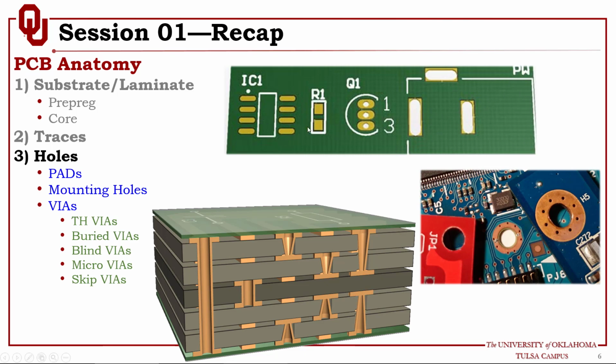And these, they usually call single layer pads for surface mount components, and these are called through hole pads for through hole components. And sometimes they call these multi-layer pads as well, also for through hole components. The footprint, for instance, is a collection of pads. IC1 is a collection of 8 pads constructing one component. R1 is a collection of 2 pads. Q1 is a collection of 3 pads, and this power connector is a collection of 3 slots or 3 pads.